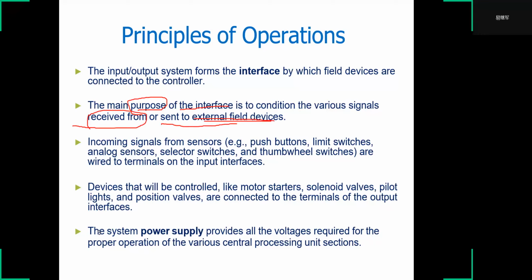Incoming signals from sensors, push buttons, limit switches, analog sensors, selector switches, and thumb wheel switches are wired to the terminals on the input interface.